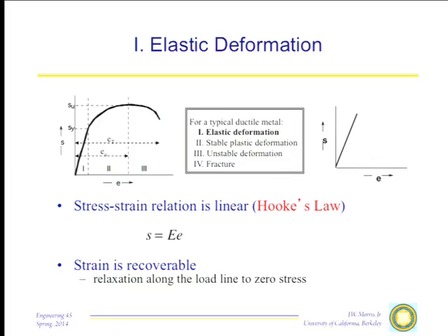In fact, virtually everything you will see, if you pick up textbooks on the elastic analysis and so on, assumes isotropy, assumes elastic isotropy. So there are only 2 independent moduli. That is a bit deceptive, and you have to be a bit careful with that too. I'm not going to belabor the point, but let me just warn you. Structural materials, structural metals, structural ceramics, are generally isotropic because they consist of many, many randomly oriented grains. And the average of those grains, since they're equally likely to point in all directions, is an isotropic behavior.